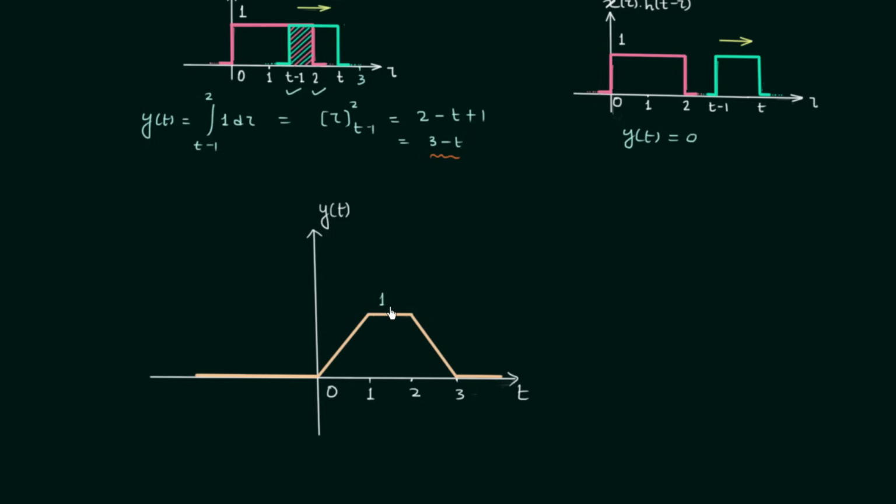So this is how the waveform will look, but I am interested in finding out the expression of yt in terms of ramp signals, and for this we will use the knowledge we have obtained from the lecture on mathematical representations of signal waveforms. Initially we will follow the signal flow. It is like this. So yt is equal to 0, but when t is equal to 0, you can see the upward turn, and whenever there is an upward turn, we take a positive sign, and after taking the upward turn, the flow of the signal will change.